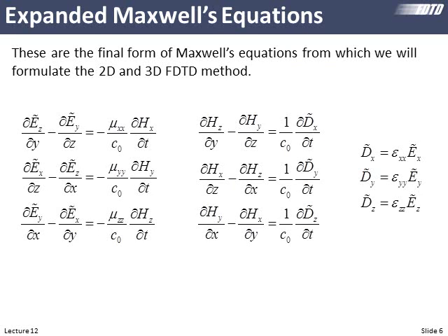We began deriving our update equations by taking our three remaining Maxwell's equations, and I guess I'm being lazy calling those Maxwell's equations. One of them has the B equals mu H constitutive relation substituted into it, so it's not purely Maxwell's equations anymore, but we have Maxwell's equations. We expanded those, and now we have a set of 9 coupled partial differential equations.